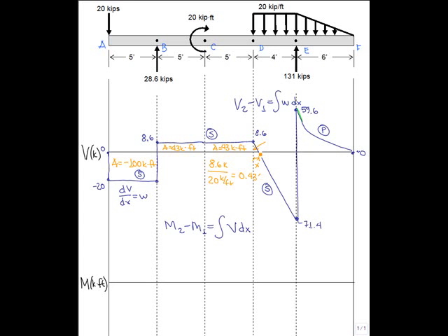Now we have the distance. We can then compute the area of that triangle is 1.85 kip feet. And the area of the triangle in the remaining part of that region is negative 127 kip feet. Now, in this piece between E and F, we have a parabolic spandrel. Noting from our RDC that the equation for the parabolic spandrel is 1/3 base times height, we calculate this area to be 120 kip feet.